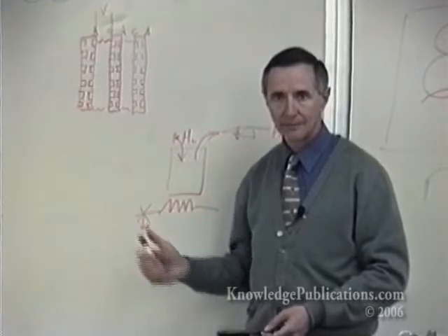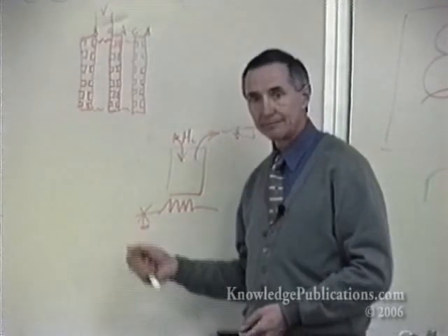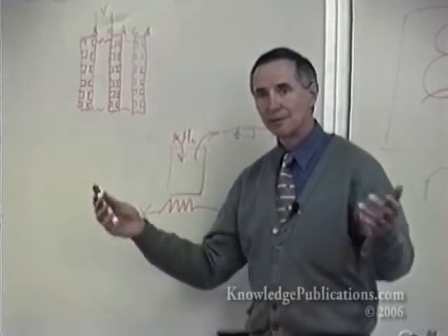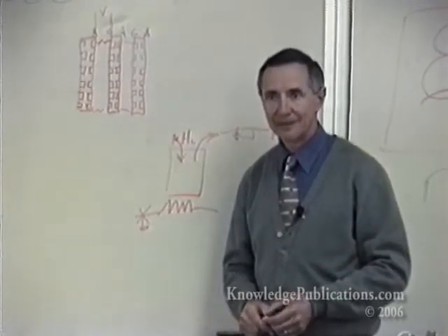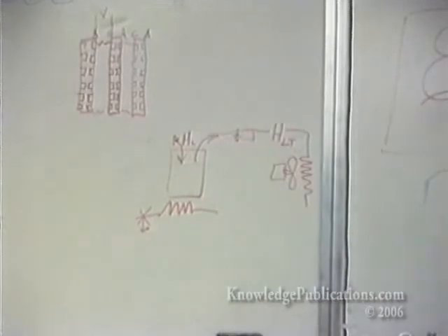What was the heating temperature you're using on the hydride itself? 80 degrees C. That's fine. More is better, but that could work. If you go to a phosphoric acid fuel cell, you have a much more efficient hydride heat pump. You can do a lot more, using a higher temperature or a medium temperature fuel cell. If you go to phosphoric acid at 200 degrees C, you've got a much more compact hydride heat pump. Yeah, but your cold sink on this side is going to be 25 degrees C air. That's true. That is true.